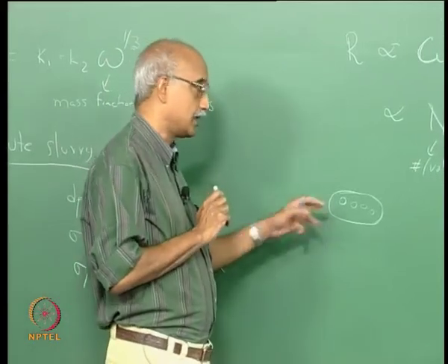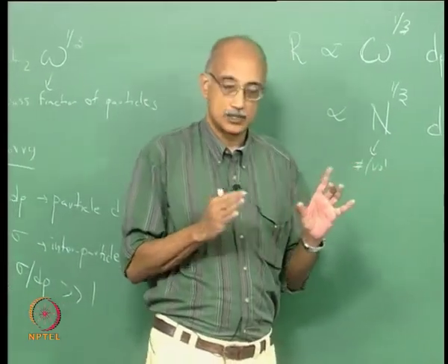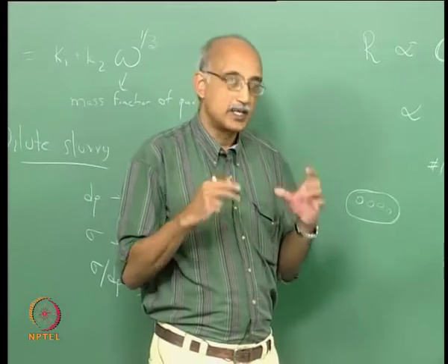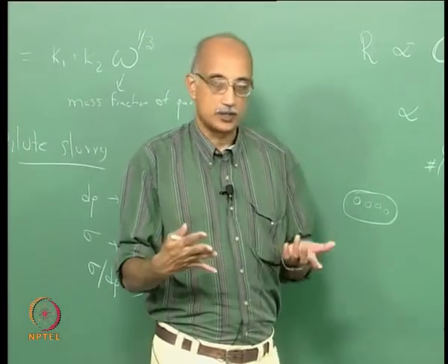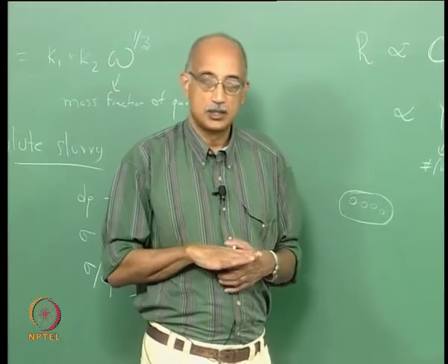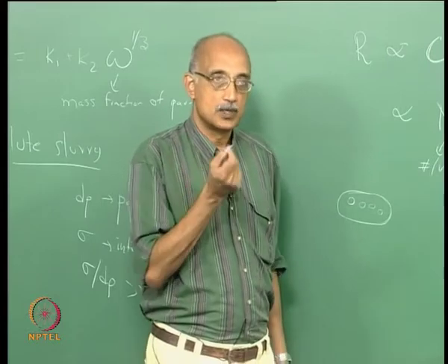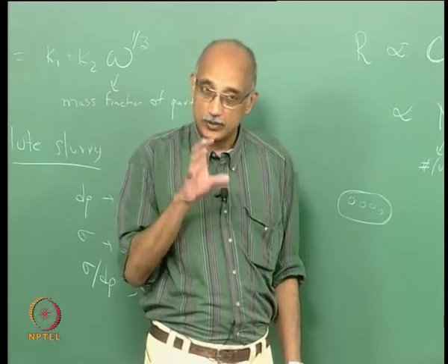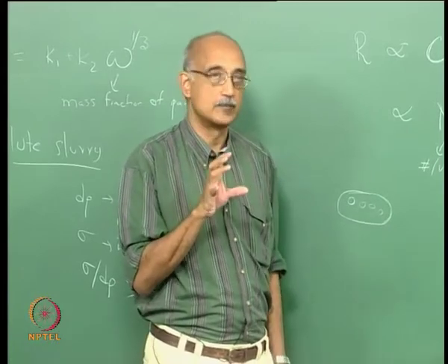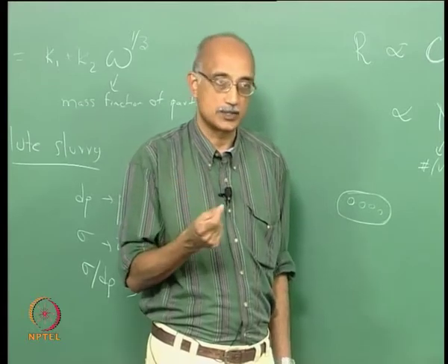However, you have to be careful in that interpretation, because that assumes that the total volume of material is also variable. But if you have a given volume of material and you want to maximize the rate of abrasion or rate of polishing, then what you should try to do is make that given volume of material into as fine a distribution of particle sizes as possible, because for a given volume or mass of material, smaller particles will give you much greater surface area.